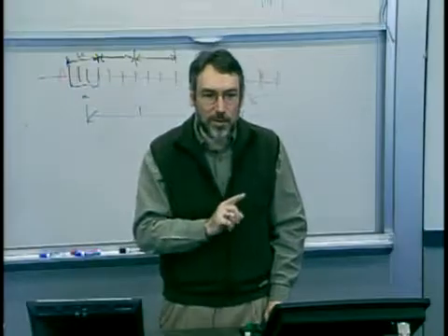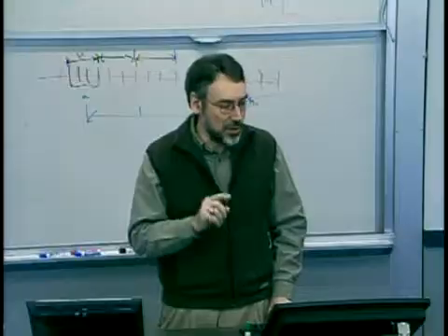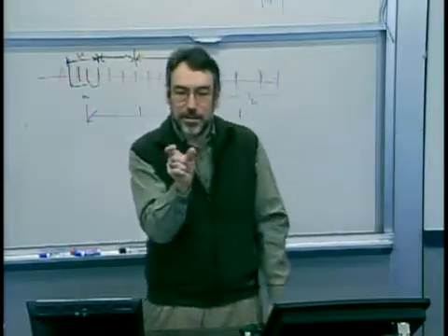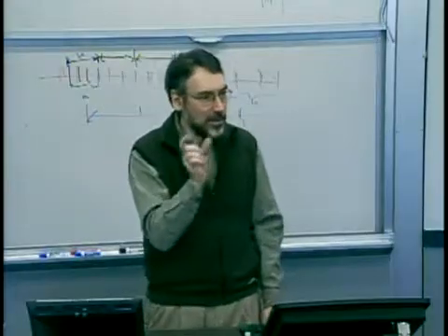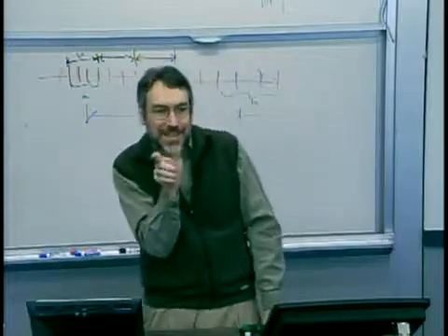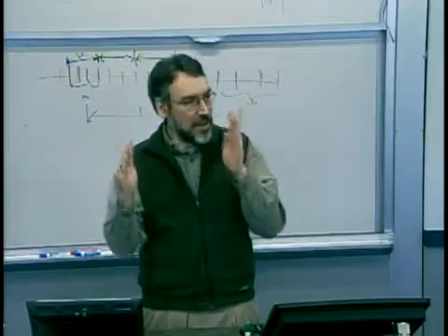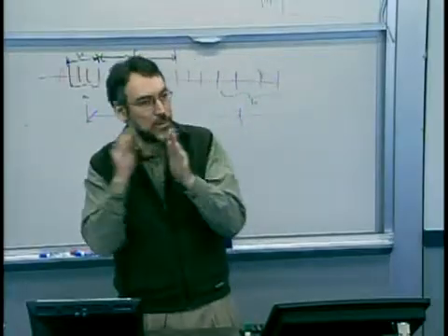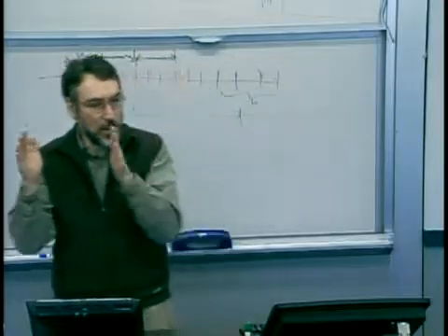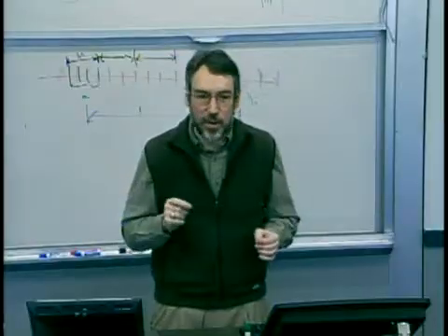If you also want to worry about mean, and you often do, another measure is the CPK. And what that looks at is the shortest distance, either on the right or the left of the chart, between your spec limit and your mean. How many sigmas apart is your mean from one of the spec limits? And divide that by 3 sigma on either side, right? And so now you're penalized for being offset from your target.